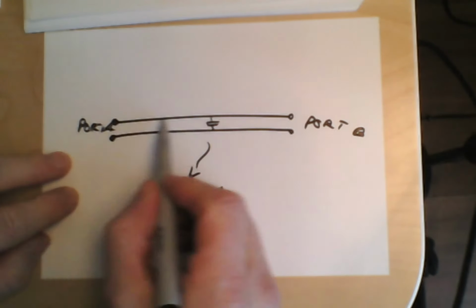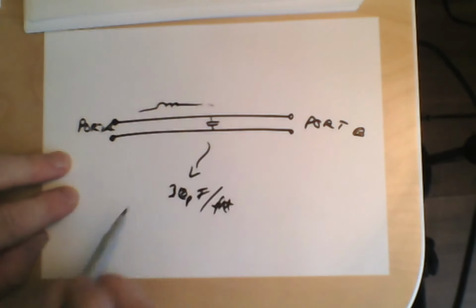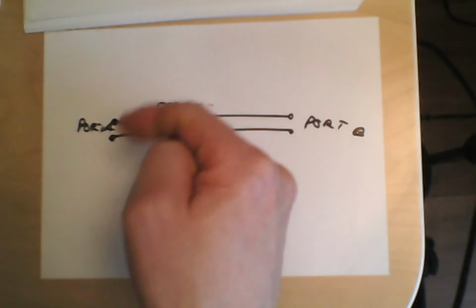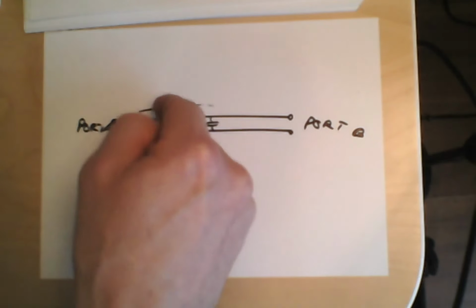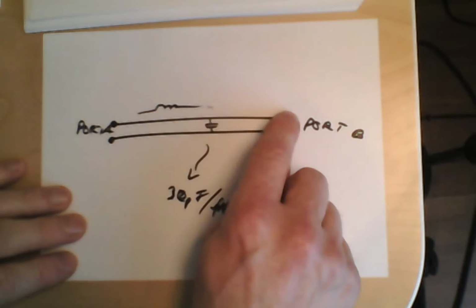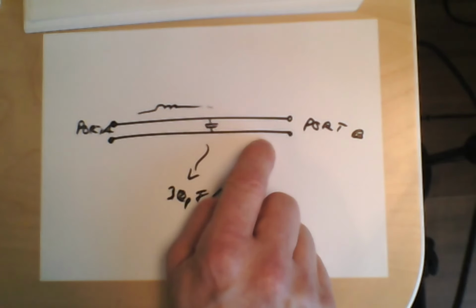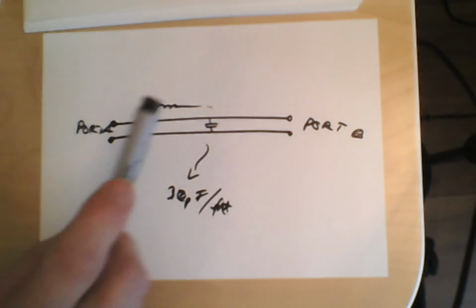And then we have long wires. Long wires means that it has some inductance on the wire. If the current flows, it generates the magnetic field around it. There's some magnetic coupling between these, so practically it has inductance on that model. In addition to that, the wires are thin because then you don't need that much copper and the wire is cheaper.